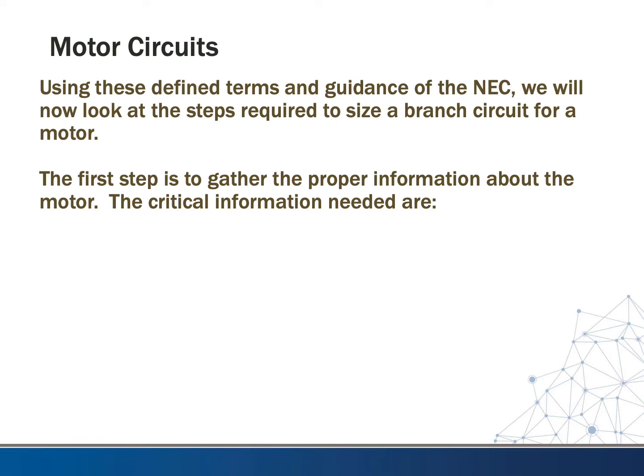Using these defined terms and guidance of the NEC, we will now look at the steps required to size a branch circuit for a motor. The first step is to gather the proper information about the motor. The critical information that we must have is, first, is it single phase or 3-phase, which whoever is supplying the motor should be able to tell us.